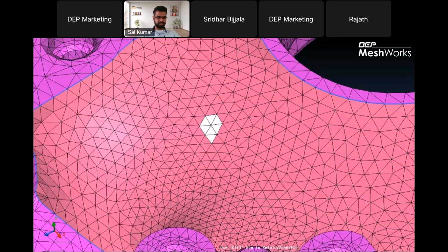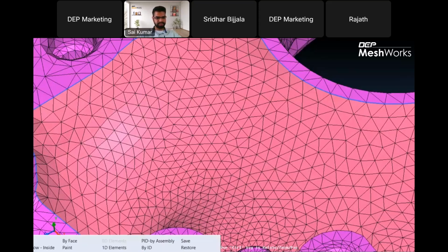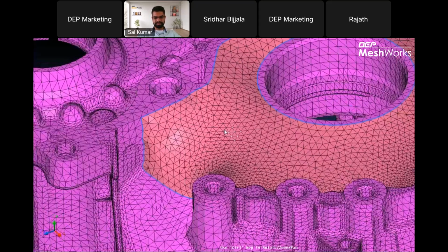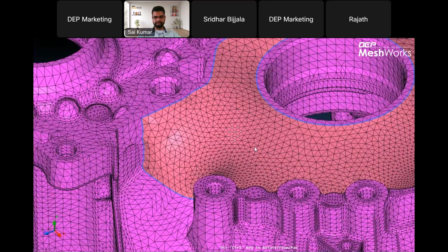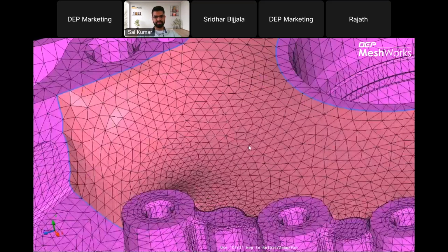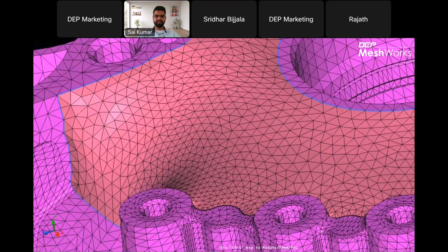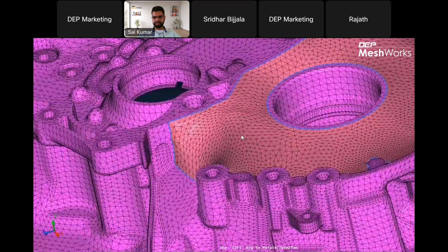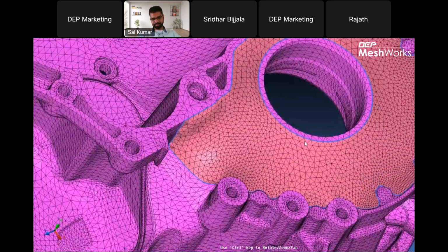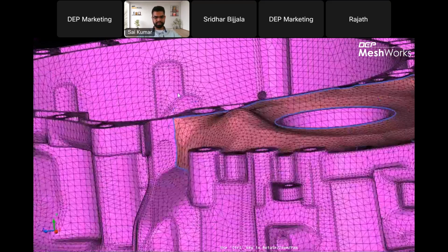I'll be going with the offset, and we click on that, and here we have this panel in which we can select the nodes, which is nothing but the element selected previously, and we can click on offset plus or minus to adjust the height accordingly, as you can see. And when you click on accept, offset is completed, return out of the panel,